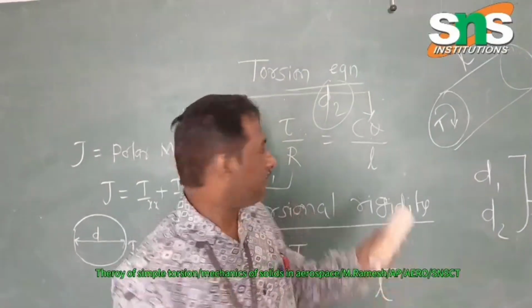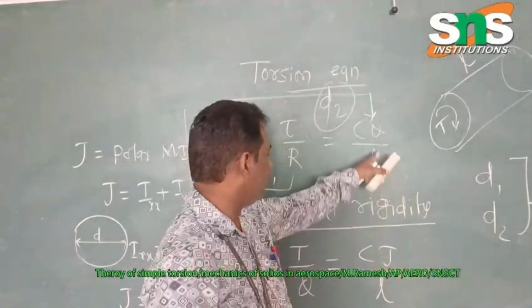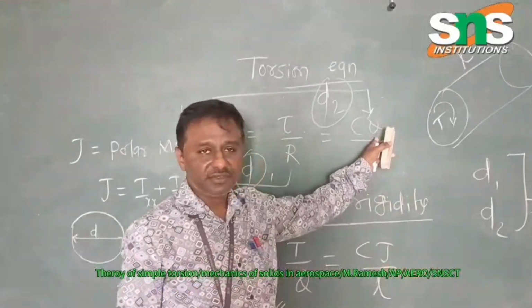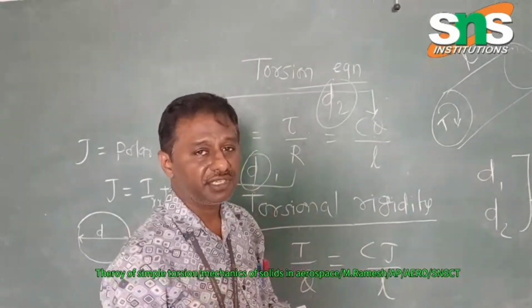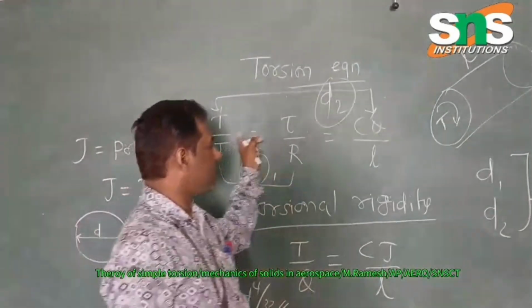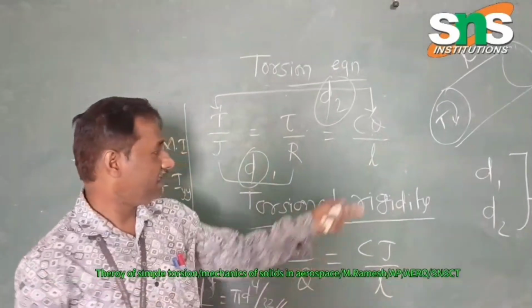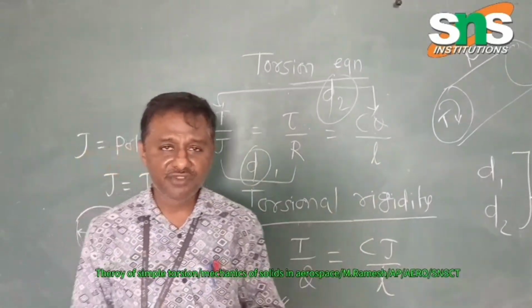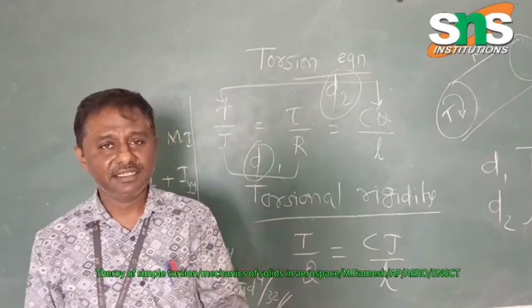It should withstand the maximum stress as well as the angle of twist. Based on that, we are going to select the diameter for the particular section based on the shear stress or based on the angle of twist. So combined, you have to concentrate, get the diameter of the shaft, and compare which one is the greater value. That will be the answer for the shaft.